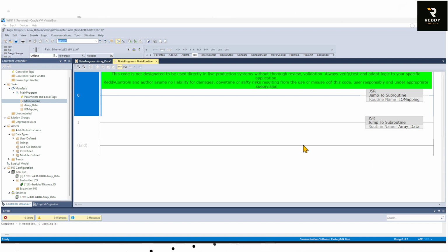When I first started using CompactLogix controllers, I missed the simple SCP block from the SLC 500 days. The SCL instruction exists, but it's only in structured text. So I built my own ladder version, and it changed how I handle every analog input.